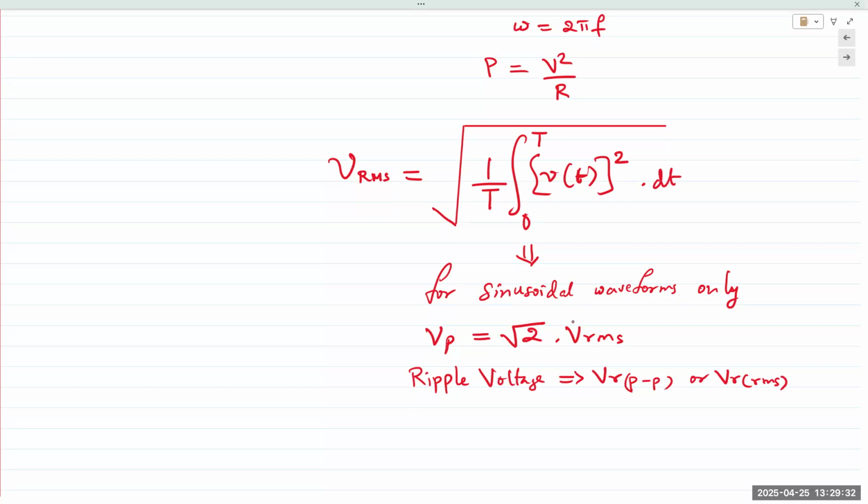So in the lab, when you performed experiment 3, you applied 100 millivolts peak to peak from the function generator, and we were measuring RMS, and we can of course measure peak to peak also at the same time. So you observed it was about 33, 35 millivolts, which is about right.